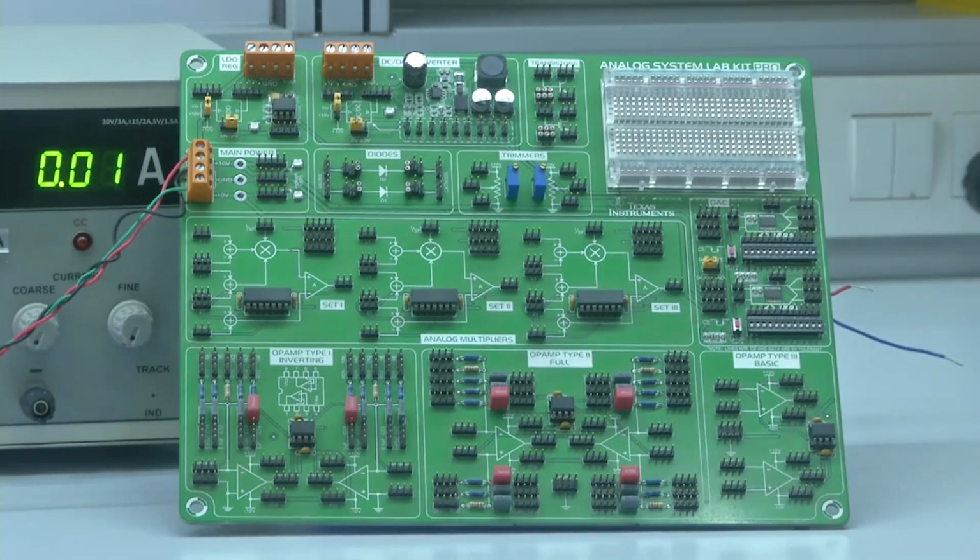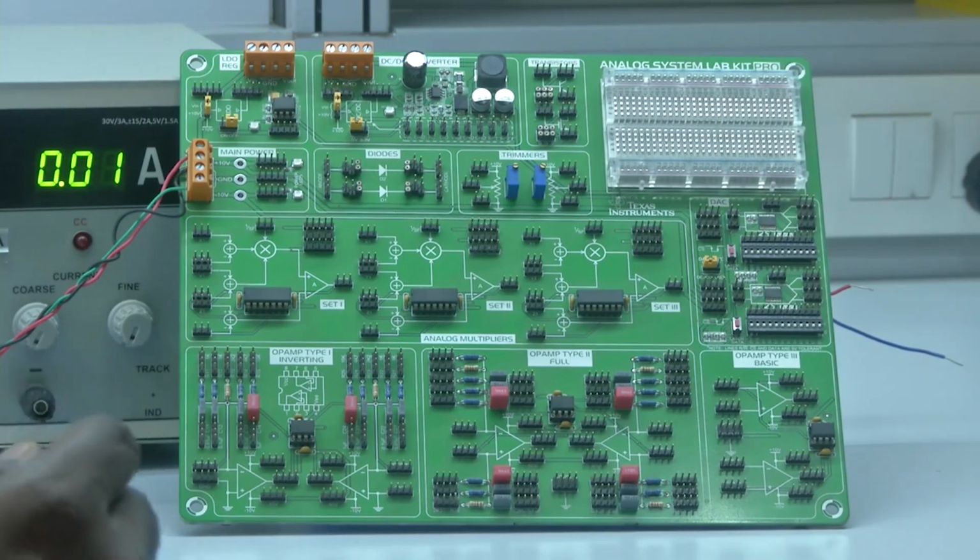Okay. Now let us see the connections for implementing both the inverting amplifier configuration and the non-inverting one. Let me go with the inverting amplifier configuration. In order to provide a gain of 10, if you recall the circuit that we have used, we require a feedback resistance of 10 times the input resistance. So I will take an input resistance of 1 kilo-ohm, so that the feedback resistance will be 10 kilo-ohm. Right. Let me take a few jumpers in order to make the connections.